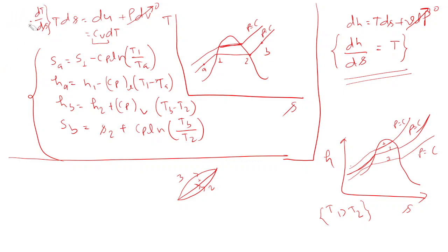Sir, what was the reason you gave for the divergence of the lines in the curve? Just simply see the slope there. Saturation temperature increases when pressure increases. So if saturation temperature is high, then its slope would be high. Any line you draw here like this and this. Okay, sir. So there should be divergence if the slope is increasing.